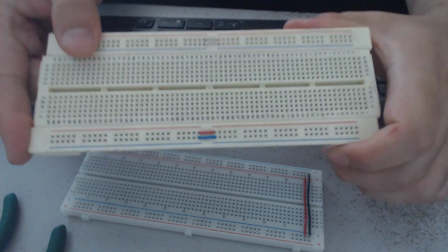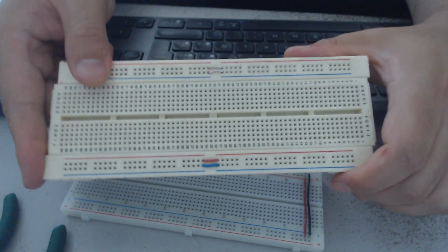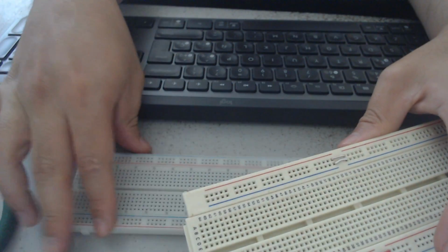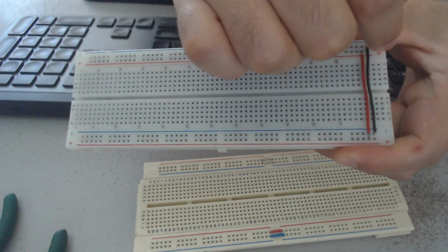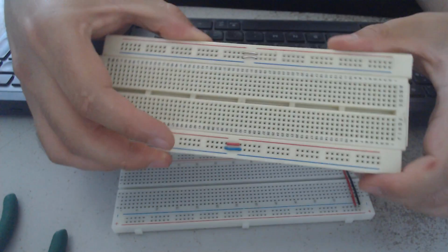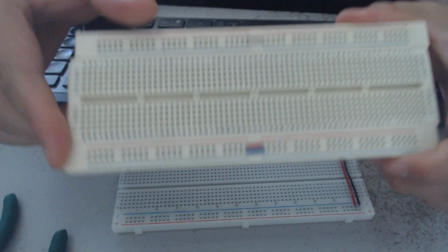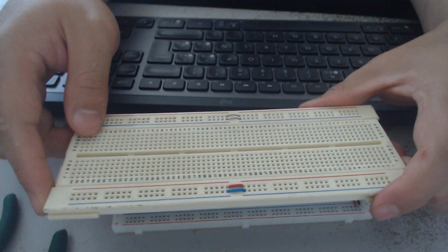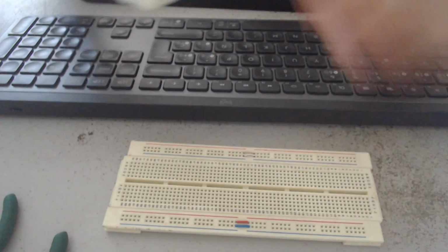I want to show you this because on this kind of breadboard you need to be careful and provide this kind of connections. For this kind of breadboard, don't worry, the whole metallic surface is continuous all along the lines. For this one, they are not continuous, so you need to provide electrical connections. Don't forget that, please. It's quite important. And you can use any of them, it doesn't matter. Let's say I want to use this. Yeah, I will use this.